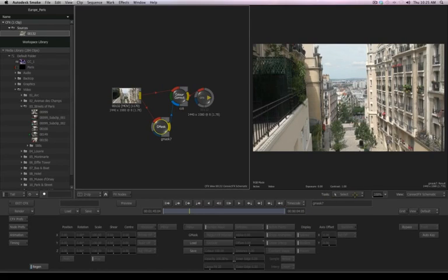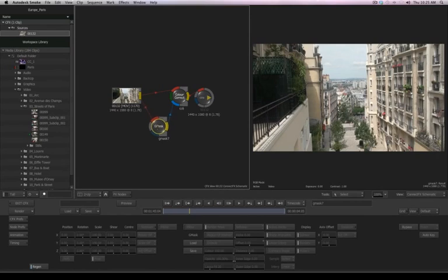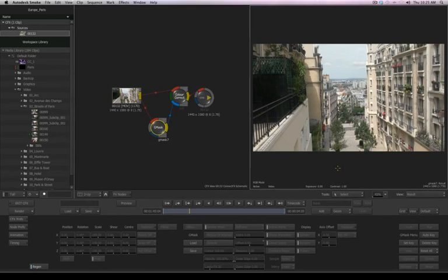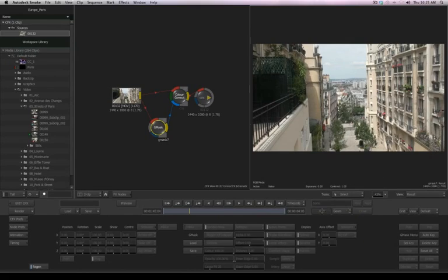The tool option is available though, and if I expand that, I could choose Draw Shape or use the shortcut of Shift-C to access this tool. Another option is, with the garbage mask selected, I click over in the result view, you'll notice there's a button reads Add, which is the same as accessing the Draw Shape tool. Either way, I can now come into the view and start clicking and dragging to create the mask to isolate the pixels that I want to have affected by my color correction.